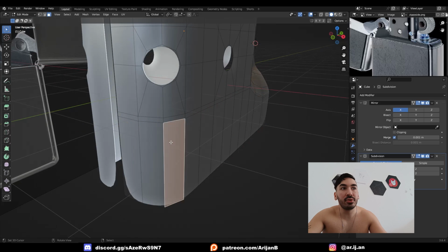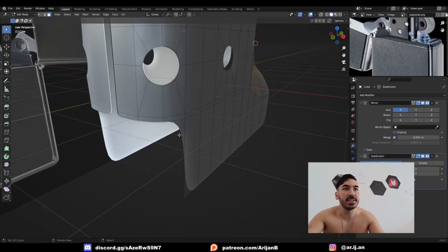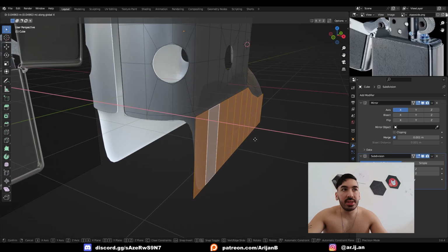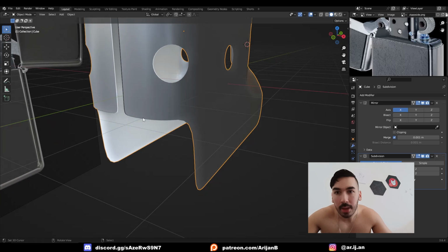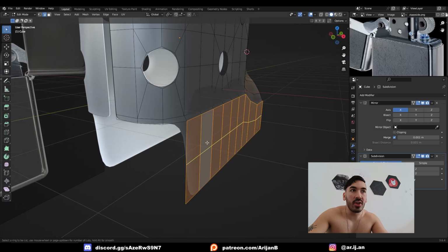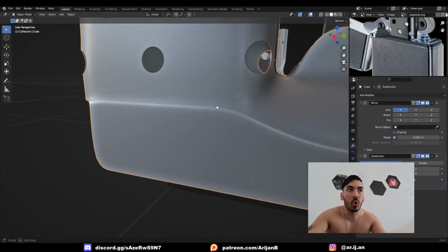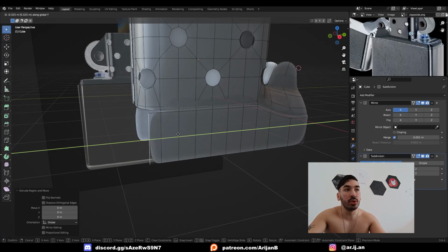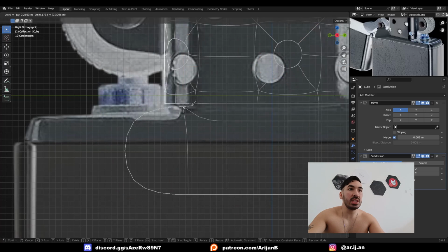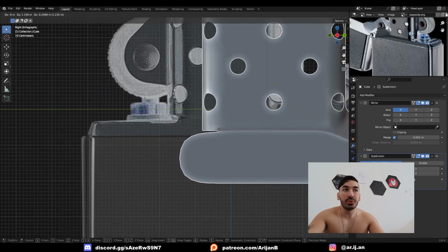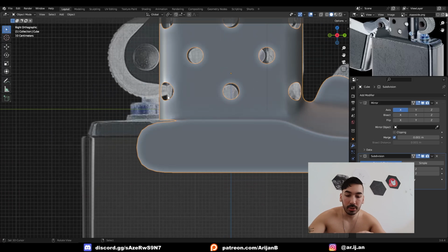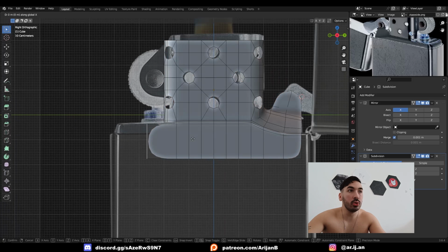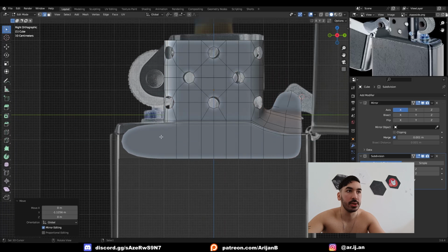Now I realize that I didn't have to do this because I'm going to have to delete these faces in the front. So we can just push this out on the X-axis. We don't have to use this Alt-S, but I just wanted to show you guys how that works. Now add another loop cut to tighten up this corner here, and then we're going to take this edge from the bottom and we're going to extrude it forwards. Inside view, you're going to see what I'm talking about. It's kind of difficult to see this on the blueprint, but I'm looking at it in real life, and just watch what I'm about to create, because what I'm about to create is exactly what this looks like in real life.